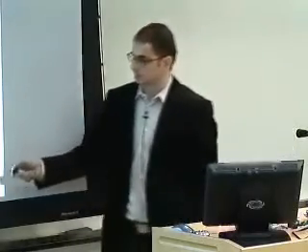Now, to give you a feeling of what a sensor network looks like, here you can see 4 different sensor nodes. This is a low-power sensor node, the Telos mote from Berkeley, very widely used. This is a more power-aware platform, the XYZ sensor node that I have designed at Yale University. And here you can see the actual sensor node interfaced to a VGA cell phone camera through a prototyping board. This is the IMote2 sensor node interfaced to the same camera through a custom design board I've made back at Yale University.